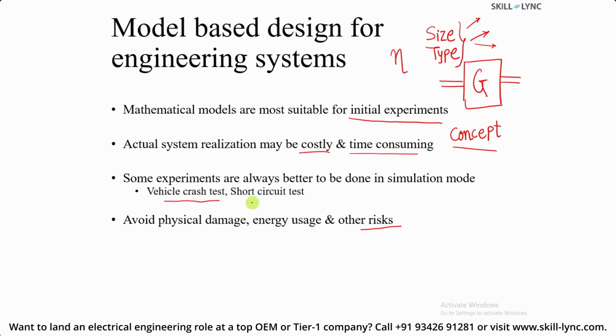For example, an electrical engineer is required to do a short circuit test, right? He wants to, let's say, test a circuit breaker or a protection device, and he wants to check whether this protection device will work on a short circuit or not. So actually he can implement this in a model based system design, and he can visualize the results: in how much time the faulty part of the circuit is isolated, and what is going to happen if the fault is persistent or if the fault condition is not recovered. So model based design is going to help engineers do all these things which are actually not possible physically, right? There are many advantages of doing such analysis or such initial experiments within your computer.